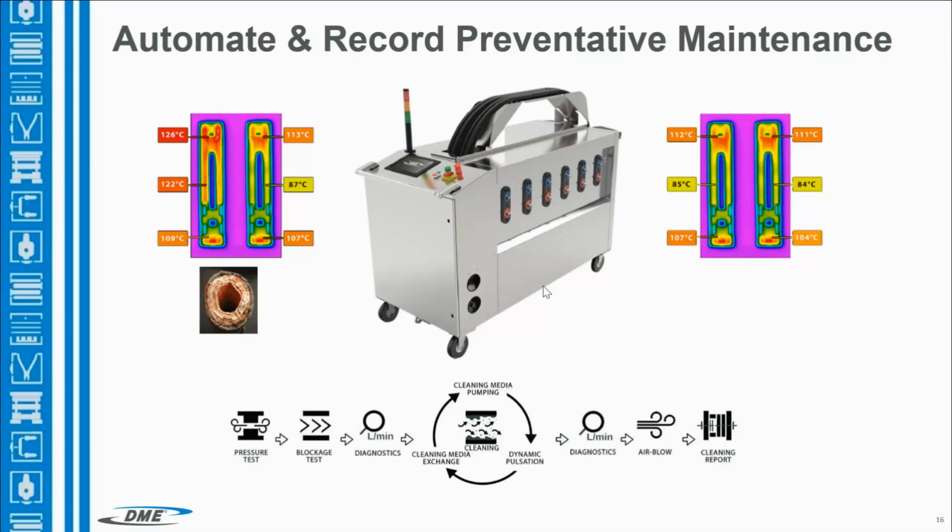that it came in at. And that's where a system like this cooling care unit goes in, and you hook it up to the ins and the outs, and it goes in and it scrubs those coolant channels with a media, and it goes back and forth, and then it's going to do diagnostics, and it's going to give you a report of how well that channel has flow rate in it, get the pressure drop between them, and it's going to really tell you that you got it back to your design. And you set your program up and you go back to that every time you clean your tool.